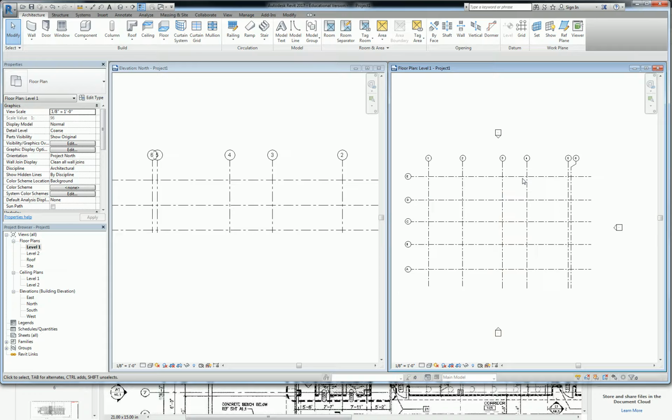The other thing I wanted to teach you in this segment is how to modify them and set them up intelligently so that they fit your architectural condition. I mentioned you can move these things, you can copy them, you can type in the distances, but one of the most powerful features in Revit is using dimensions to your benefit. You can actually move things using a dimension string, which is pretty sick.